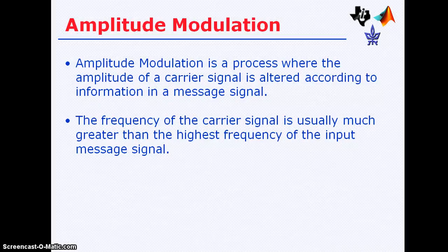In communication there is a limitation to transmit a baseband signal to higher distances. Because normally the baseband signal or the information signal which is being generated is of low frequency range, it is difficult to transmit this particular signal to a much higher distance. In order to avoid this drawback, we increase the frequency of the signal which is to be transmitted, so that this high frequency signal can be transmitted to a much larger distance using any of the modulation techniques which are available in our communication system.